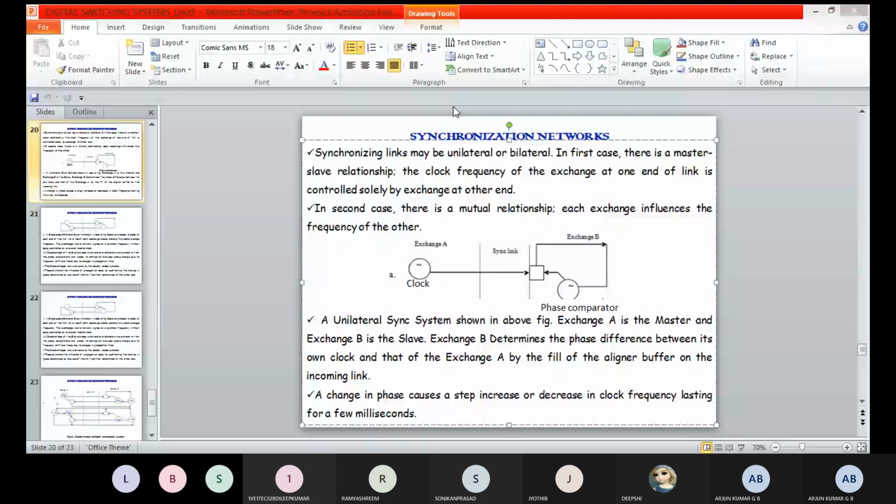See, during the no load condition the motor rotates at the synchronous speed only. Synchronous speed means the rated speed. If you put some load on the motor, automatically the speed gradually decreases a little bit, 5 to 10%. That variation is called slip. The variation between the load and no load condition is slip. Some slip difference will be there.